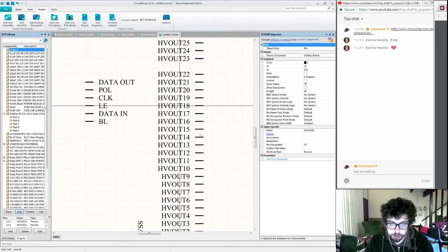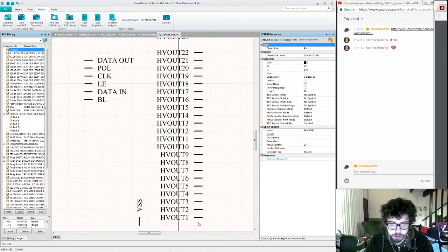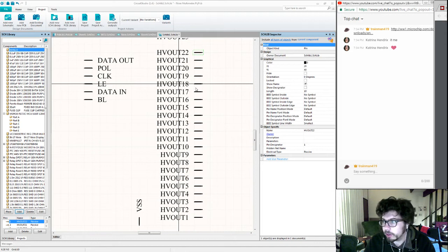If I swap one or two of these high voltage pins, it's just a software fix. And I'll probably even wind up doing some pin swaps on these so that whichever pins I have connected across will just run straight across the top of the board to the Nixie tubes, and then I'll map individual numbers to pins in software. That makes the PCB routing a lot easier.